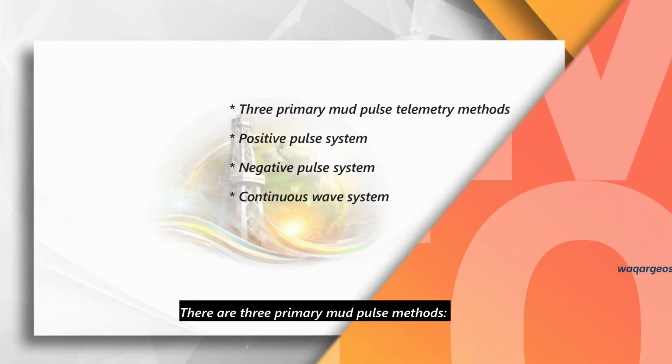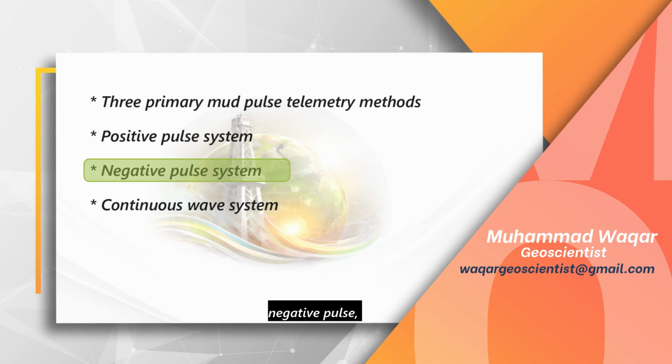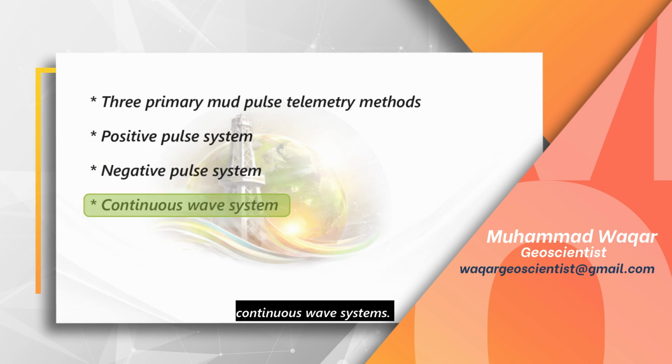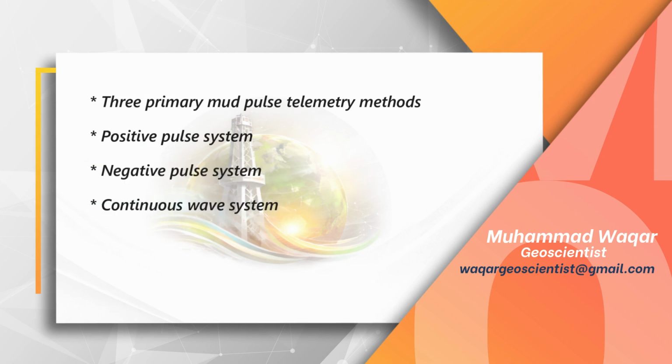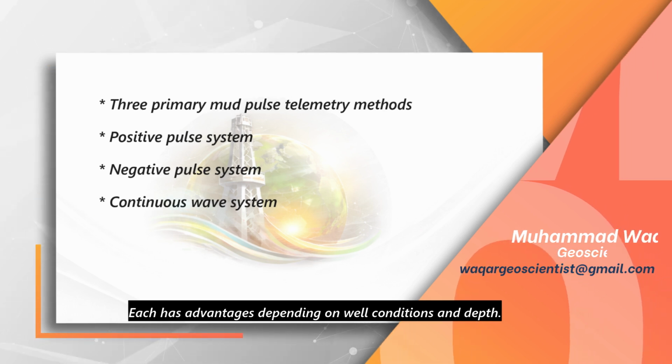There are three primary mud pulse methods: positive pulse, negative pulse, and continuous wave systems. Each has advantages depending on well conditions and depth.